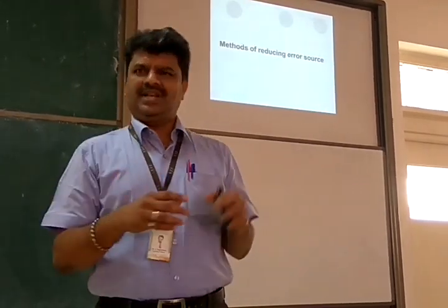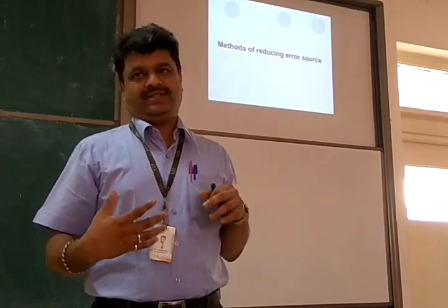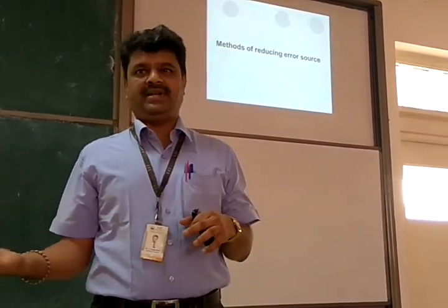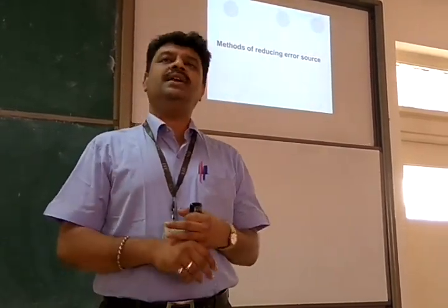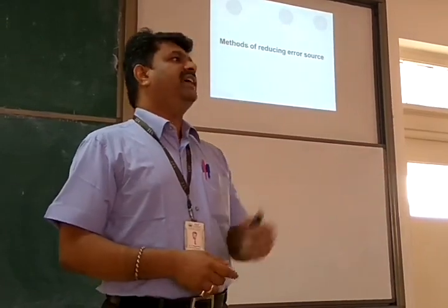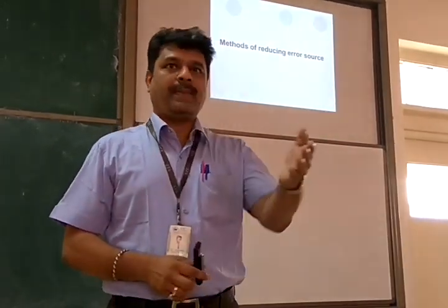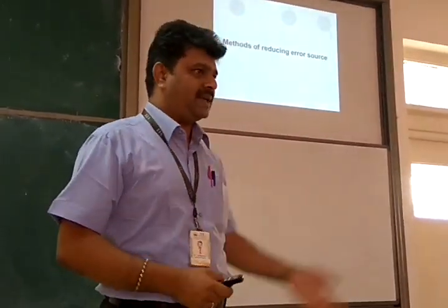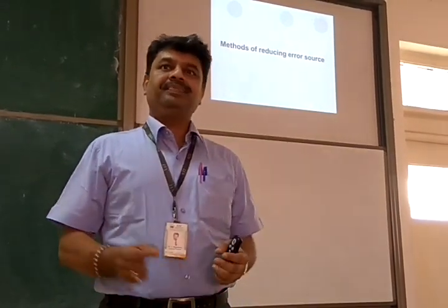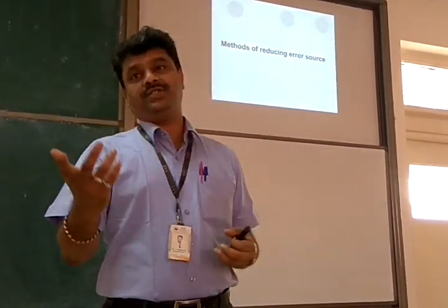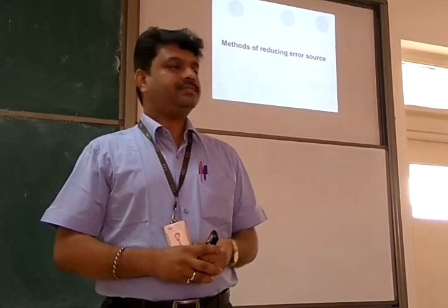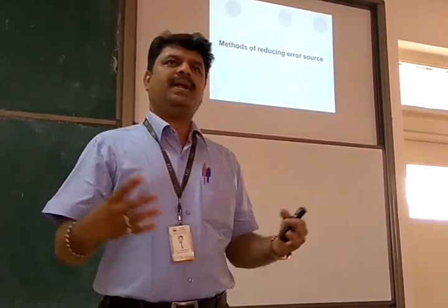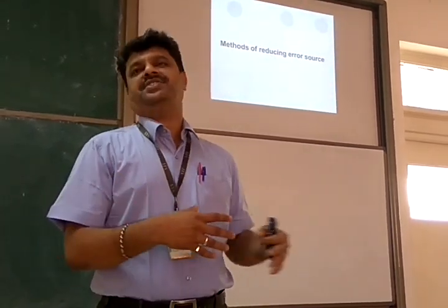Not all measurements, but some instruments will be affected by some parameters. Like humidity. For example, we have a capacitance-based level sensor, isn't it? Humidity will affect the capacitance value a lot. Like that, certain parameters will affect certain measurements.